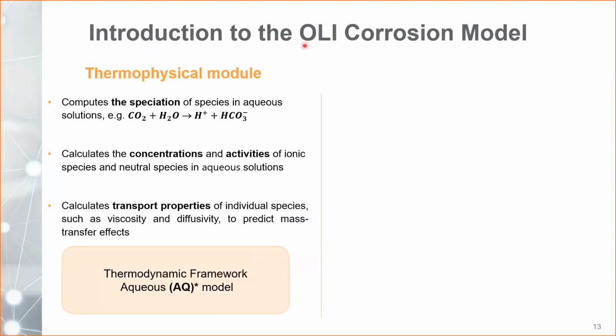When we are working specifically in the OLI Corrosion Analyzer, we need to keep in mind that the only framework that we can use to calculate corrosion rates is the thermodynamic framework AQ, or the AQ model. We are working currently to also include the MSE corrosion, but that is under development. At the moment, anything that has water content can be modeled with the AQ model. That is something I wanted to highlight here: only the AQ model can be used for the OLI Corrosion Analyzer.